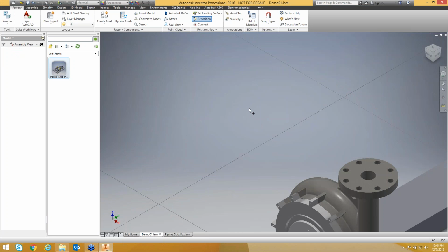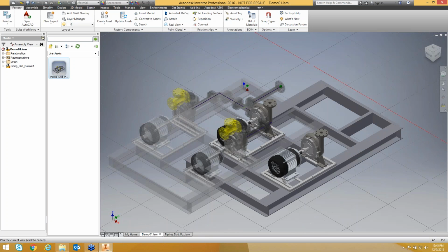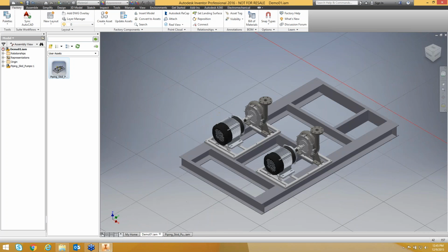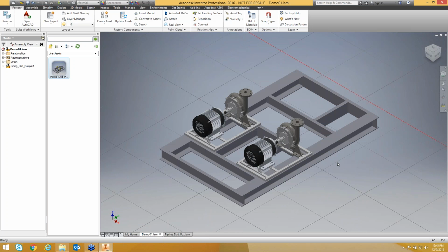Notice, let me get out of there and get out of the second placement. Notice I lost all my piping. And so again, that simplify step is very, very important. If you're going through the process and you realize, oops, I don't have the pipe that you used, even the cable and harness, to some degree even the frame generator, you might actually lose it.